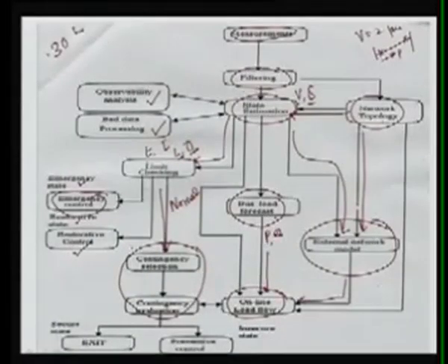So this is the information required for your online load flow. We know that in load flow analysis, we require the real power and reactive power at the buses, and at the same time we require the network topology that is coming here and the external network, and then we can run the load flow that is used in the contingency evaluation process.